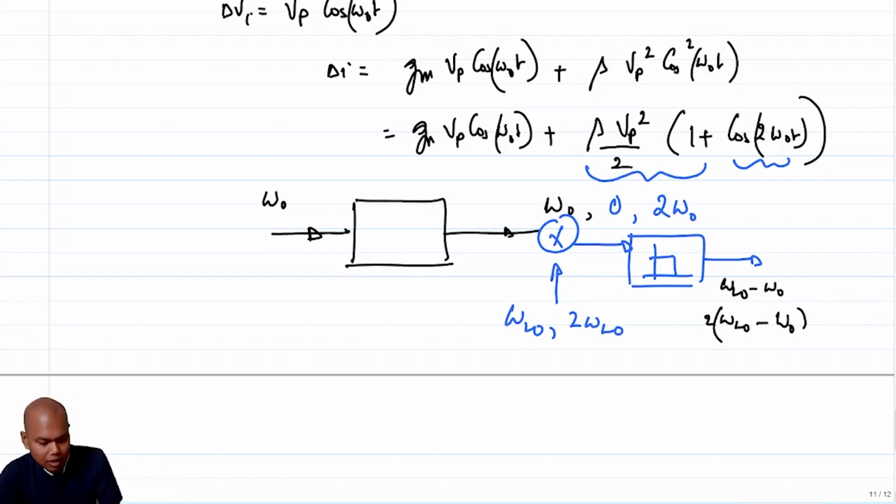signal, right? Not only that, the swing at the output of the LNA is not just governed by the fundamental component. It is also being governed by your distortion components, right? So if the distortion components are significantly larger than, or even comparable to, the fundamental components, then it can also saturate the following stages. Okay.